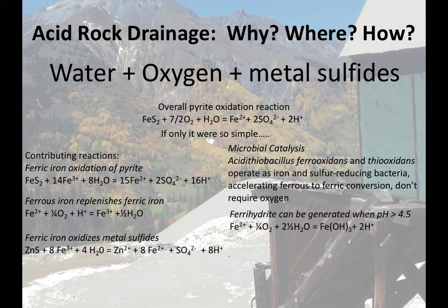And this happens once the pH starts to climb, and this is our goal. With limestone reactors, we add carbonates, we pull the pH up, and the iron, once it starts to complex, actually starts to produce more acidity again, and it wants to drive itself back down. And so this is kind of a secondary acidity reaction.